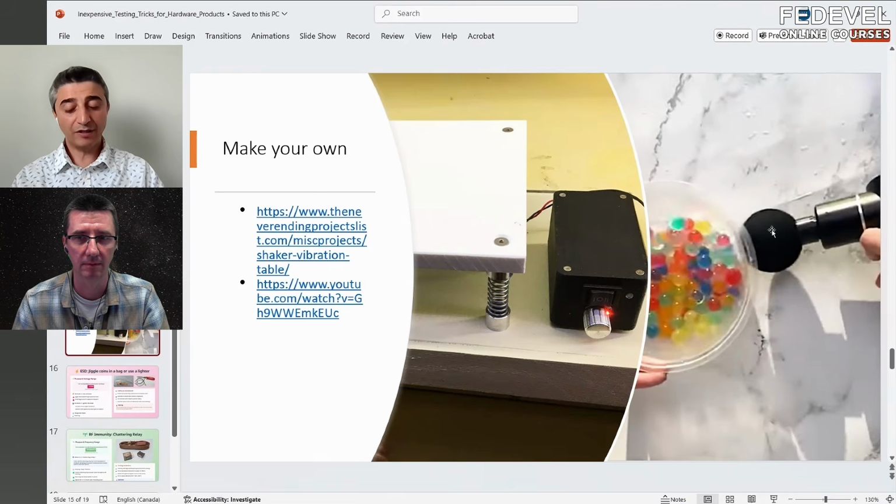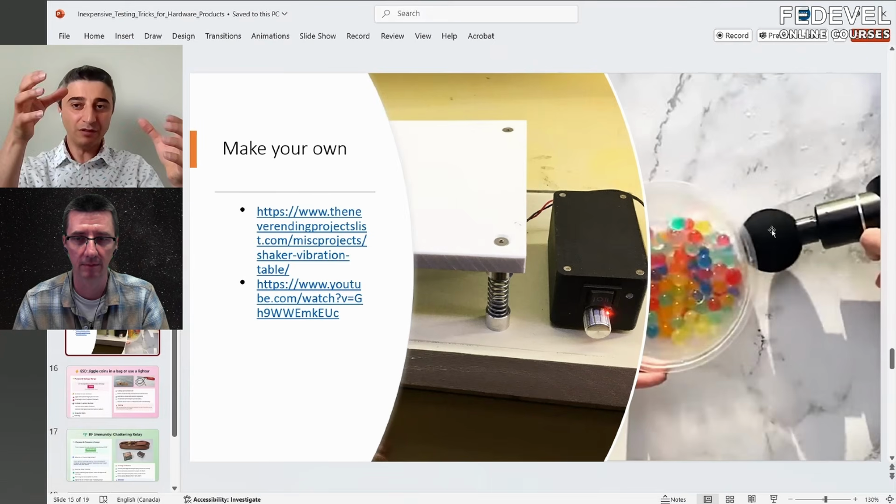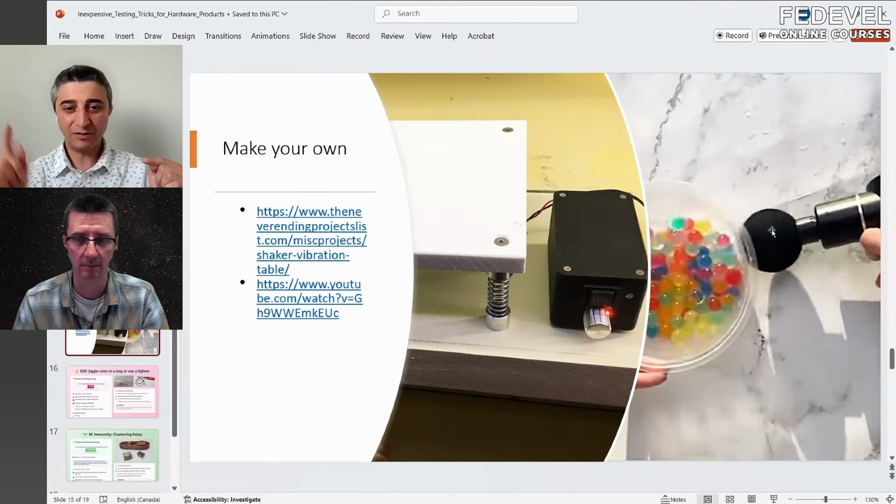So there are certain orientations. If, for example, you're shipping your product and mounting it in a box vertically, that test might not expose the issue. Maybe if you put it horizontal or on its side, it might cause the issue to happen. So I agree with you. The testing will be more successful if you use the right orientation. Go at the corners of your product, the bottom, the top, make different orientations so that you can cause the failure to happen. And this is an easy one. It's not really complicated, but you see the issues right away rather than waiting until they happen in the field.